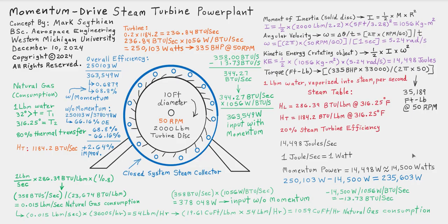So if you heat something and there's heat output, and let's say you raise the temperature of water an X amount of degrees per second over some pounds of water, then you can calculate the BTUs per second and then multiply it times 1056. And then you might want to multiply it times 1 over 0.8, and then you're able to figure out how much BTU is actually in that flame, because energy is conserved. We can't create or destroy energy.